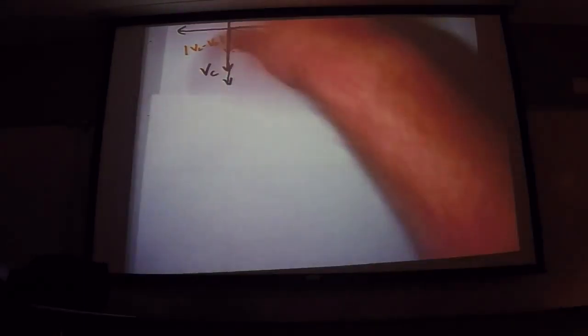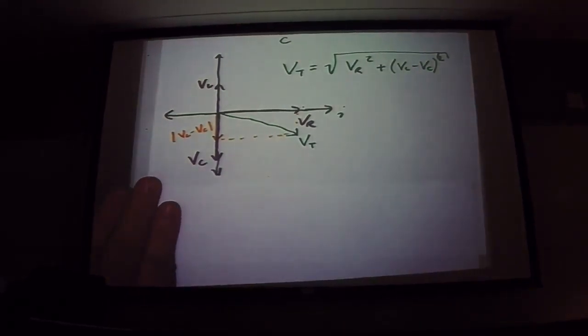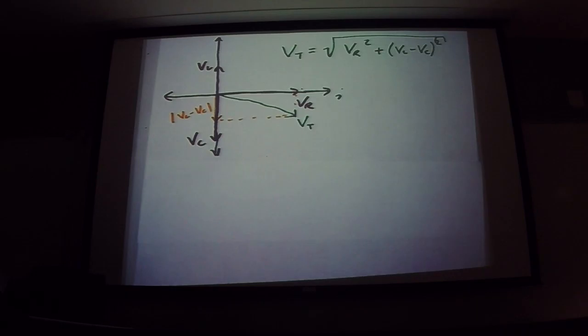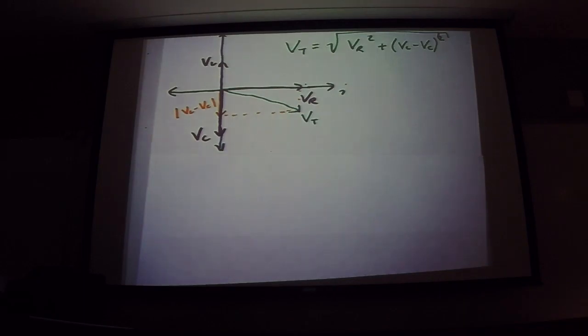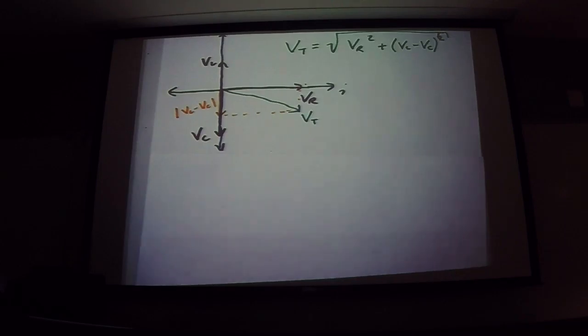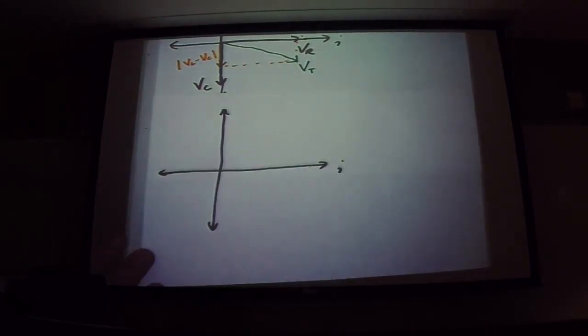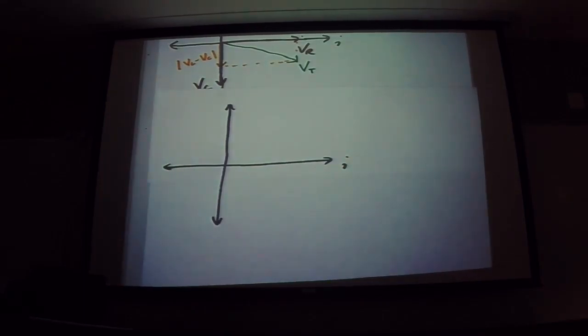All right, so what I'm going to do with this is take this and divide every term by the RMS current. If we divide all these voltages by the RMS currents, remember how we got those voltages. Those voltages came from that reactance. So if I divide the RMS voltages by the RMS currents, I'm going to get a chart of reactances, and it's going to look very similar to this. So we're going to draw our axis again. And once again, we're going to say that the current is going along here, even though the reactances themselves don't have a phase, their corresponding circuit elements do.